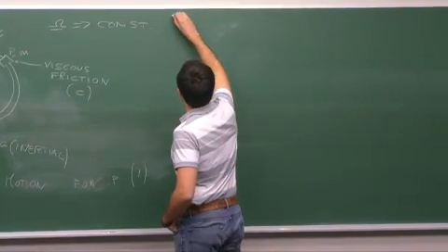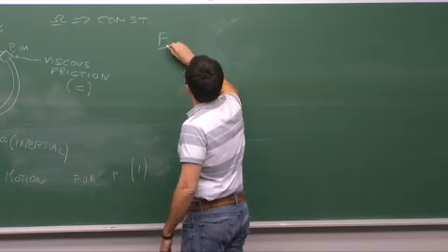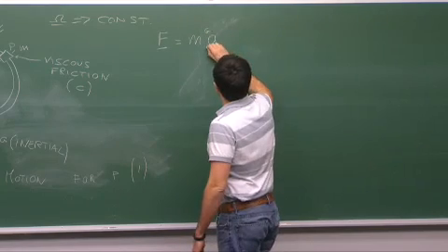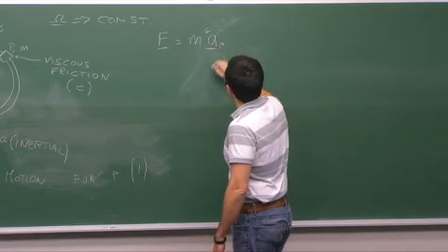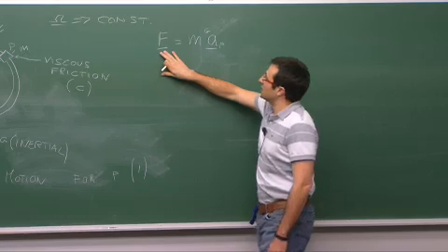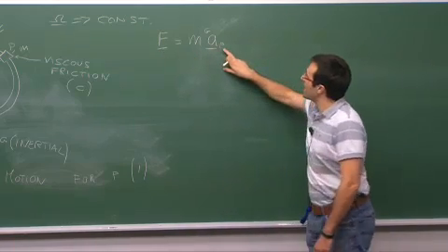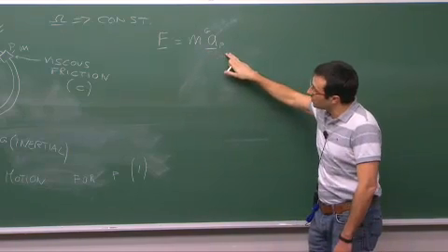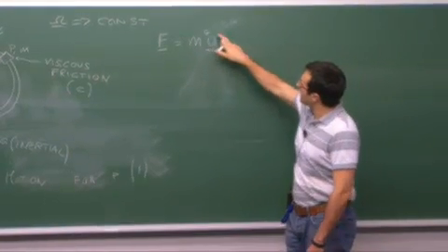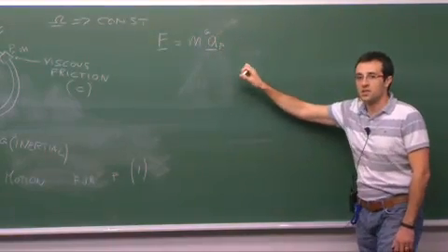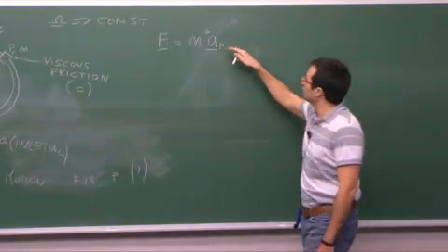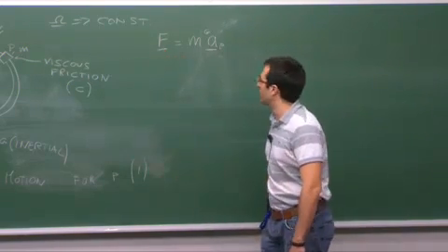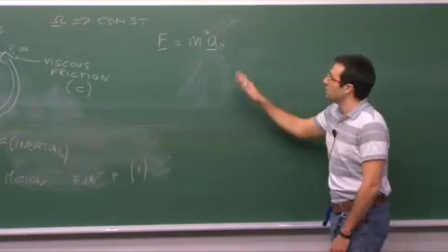Yeah, okay. So differential equations of motion for a particle come from Newton's second law, that's what this is called, which tells me that the resultant of all forces acting on the particle P of mass m is equal to mass times the acceleration of the same particle as seen by an observer fixed to the ground. This is something you need to understand. So if you stick in here the acceleration of the particle P with respect to another, non-inertial reference frame, you cannot do it.